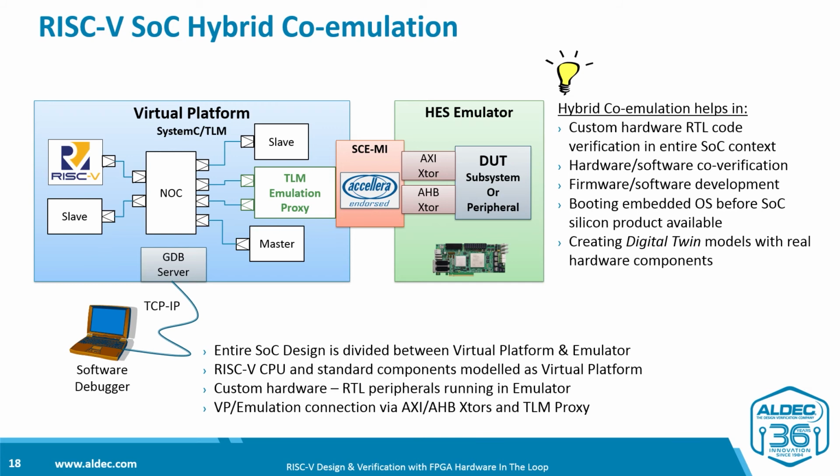And if hardware models are not available, virtual platforms are quite willingly adopted by software developers at the beginning of the software development process. However, some subsystems or peripherals, IP cores, are not available as virtual models, and in such a case the virtual platform alone is incomplete and requires some dummy code to substitute for missing components.